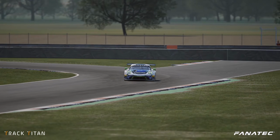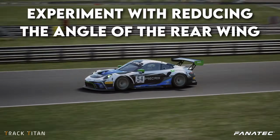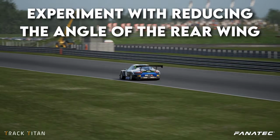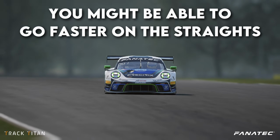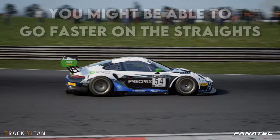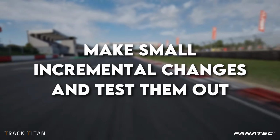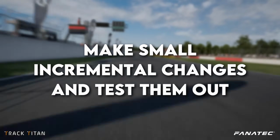Now, if your car feels pretty good from the get-go, you might want to start experimenting with reducing the angle of the rear wing, especially if there's some long straights on the track. This way, you might be able to increase your top speed and get a quicker lap time in. But change up your setup incrementally and test it out so that you don't end up with an unstable car.